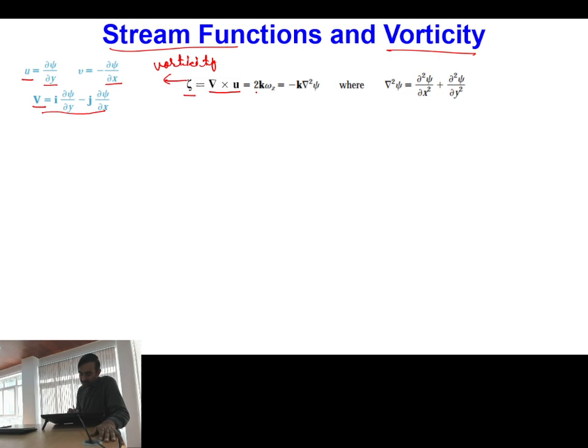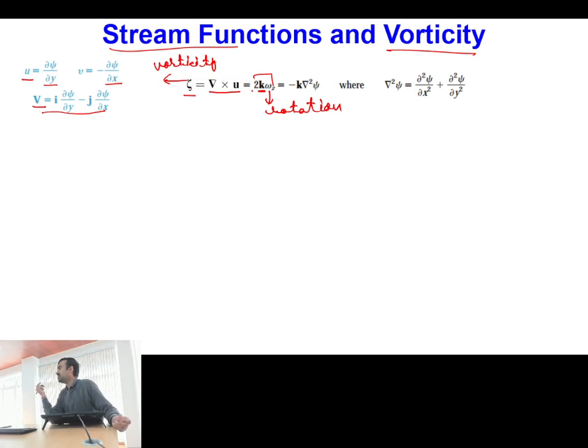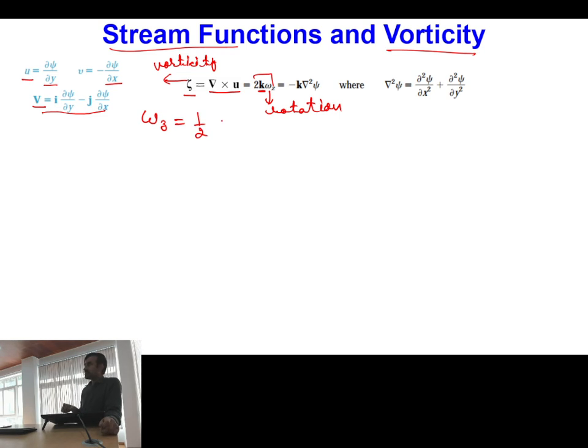So that's why this is written as, and vorticity also we know that it is nothing but 2 times the rotation. So omega z is nothing but representing over here the rotation of the fluid medium. So 2 times omega z, and this k is representing that we are considering only the z component of the vorticity field. So what I can say over here, that this vorticity, though it's a vector field, for a two-dimensional flow field, it will be resulting in a single component, which I can say simply a scalar component.